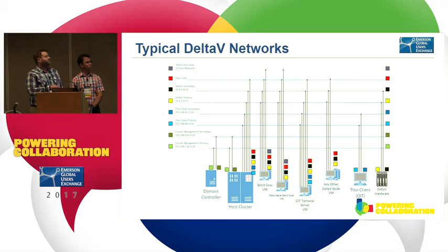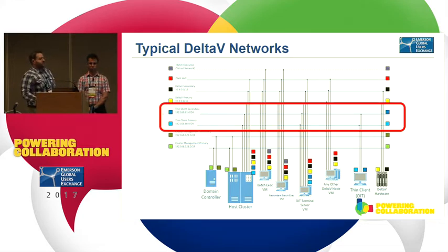And we got your plant LAN. In our case, we call that the manufacturing network. And then the batch executive. It could be virtual, it could be real, but typically only batch executives are going to be connected to that for obvious reasons. We looked at these 2 networks in particular because we have so many operator stations, so widely distributed, and also the redundancy isn't as much of a concern with the number of operator stations we have.